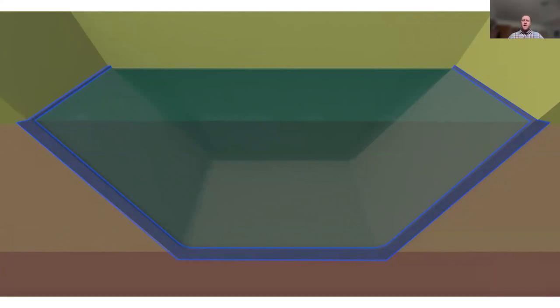And if it is clay or bentonite, so that natural material, there is a lot more seepage. So something like 5 or 10% of what's flowing in could seep out of it. So sometimes even the engineers will design for that, because even 5 or 10% of the flow can be a significant amount.